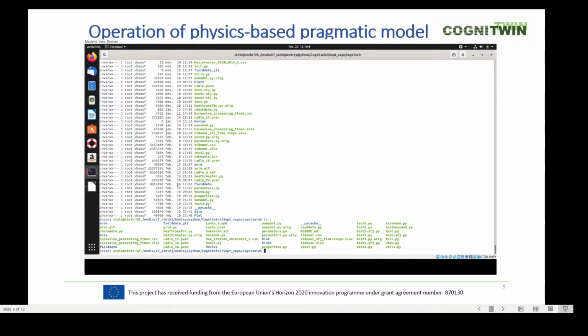Field data contains all information from Sidenor when it comes to the operation of the different ladles, and contains time series about how much power was used to keep the steel hot in the ladle, at what times additions were added, different alloy elements or slag formers. And it has information about how much purging gas was used at different times. This is important to drive the flow and results in different heat transfer coefficients and erosion patterns as well.